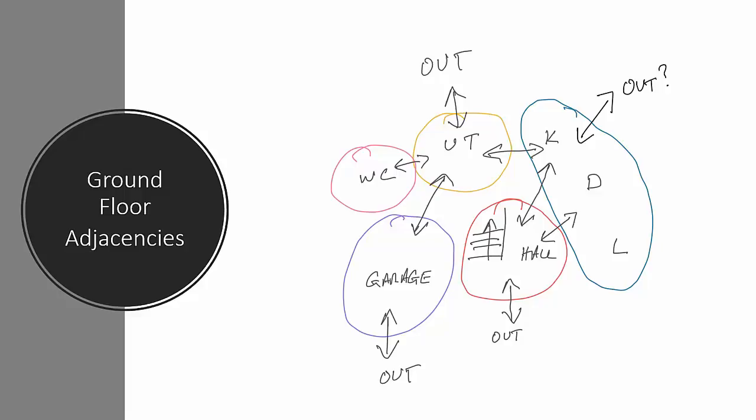In this particular instance, I have used an integrated garage, so the access to the garage that's attached to the house is from the utility room, and obviously from the garage you need to be able to get the car in and out. So there's lots of different things to think about there. Because this is a semi-detached house, you should also be considering where the wall might be that the adjoining property will fit up against.